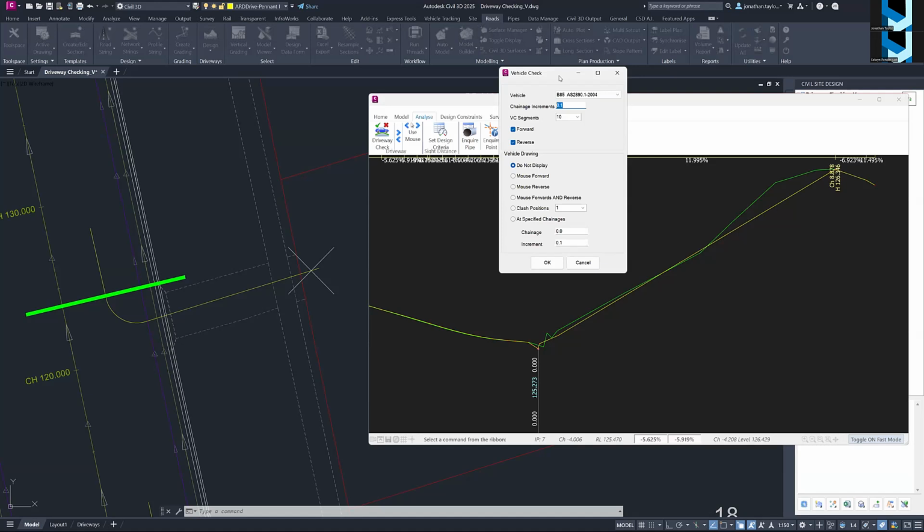It will work, but it's going to check every 100mm on a 100-meter road. You are asking it to do a lot of work. So make sure you put that number to something high and then bring it down until it's sort of comfortable for you. Every 100 mil on here is where it will perform a check for me. Okay, I'm more than happy with that.